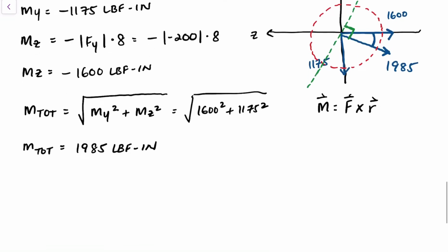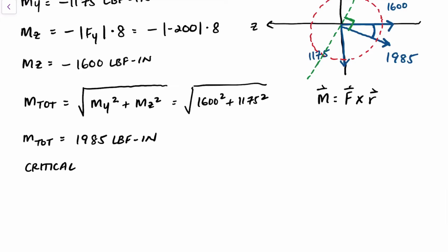So the critical section, again, the reason the bending moment dictates where the critical section is located is because torsion is applied throughout the entire cross section of the shaft, and so is the axial stress, which is applied on the entire cross section. That's why the moment dictates in this case where the critical section is. So critical section is plus or minus 90 degrees from moment vector. And we'll confirm that later.